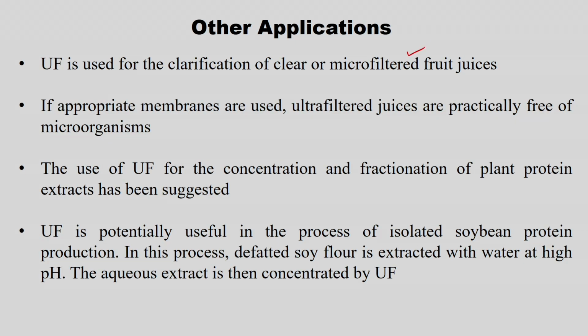The other application of ultrafiltration is the clarification of clear or microfiltered fruit juices, if appropriate membranes are used. For ultrafiltration we have also given the range of pore size and the range of pressure applied. If the appropriate membranes are chosen within the range where microorganisms get filtered, then these ultrafiltered juices are practically free of microorganisms.